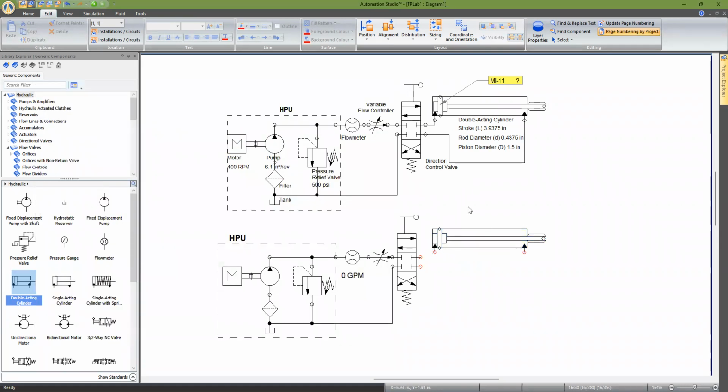So the visual aspects are now the same for the bolt, and now I have to make a connection. 2 red dots have been connected, and these two, I'll try to make it look like the other one, and now we're connected. So that's our directional valve. That's the cylinder. I left some space here so I can put all these labelings there when I show you how to do the labels. You can actually get rid of this thing for now by selecting and pressing delete on your keyboard.